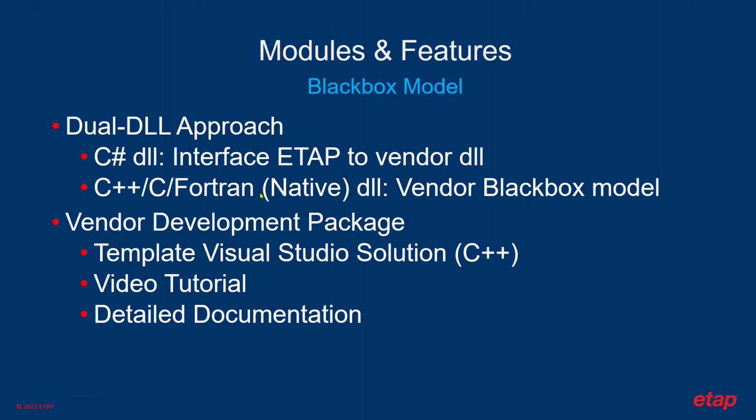The other aspect that is really important when it comes to grid code, especially once the design is done and we are doing more of a verification, is to have a black box model. ETAP offers a dual DLL approach where the vendor can have their own model written in any native language, or even a managed language, but they can have their own DLL.